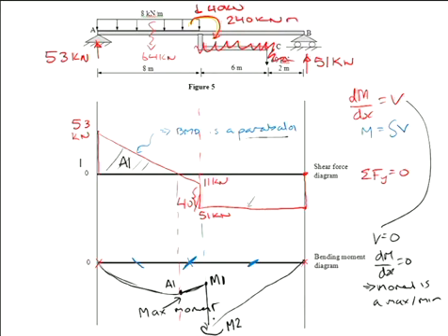Okay. That M2 value is very easy to calculate. I'll call that M2 because it's just equal to the negative area there. So that value there is 51 times, what's that, 8 metres, which is 204 kilonewton metres.